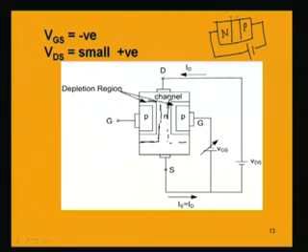So, it is P, it is N, this is positively connected, that means the current will be increasing and it cannot be controlled. Only when VGS is negative does it have a hold over the drain current, because by modulation of the depletion layer in the PN junction, the current is controlled.